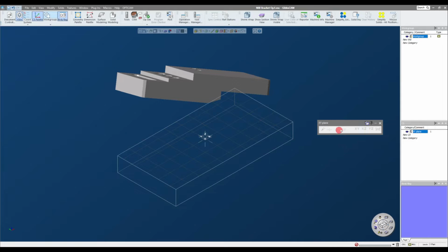Now you see everything is grayed out because we are in our master coordinate system and we can't change that one. Now our coordinate system list here is where we're allowed to create any new coordinate system that we would like. We create coordinate systems here, we modify them here. So one of the first things I like to do when I'm orienting is create my standard 3 Cartesian coordinate systems, which is going to be my XY plane, my XZ plane, and my YZ plane.